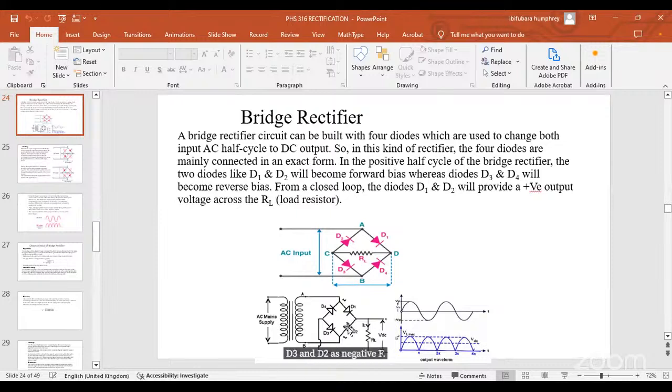That is the second circuit. As positive half, D4, D1 conducts, it gets to the junction of D1 and D2 and then flows forward and passes through the load resistor. Then for second half, D3, D2 is positive, 4 and 1 are negative, and it goes through, again, gets to the junction, passes through RL.